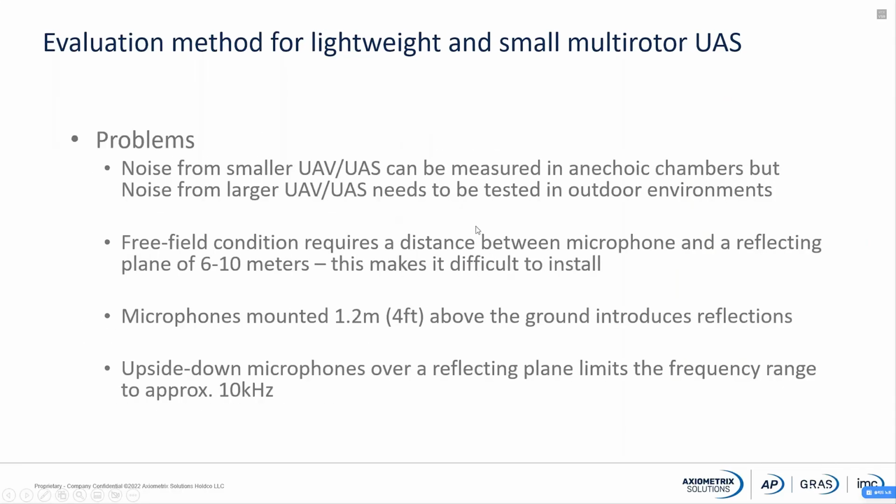So the problems we are facing are that we can do some measurements in anechoic chambers, but noise from the larger UAVs needs to be tested in an outdoor environment. Free field conditions require a distance between the microphone and the reflecting plane of 6 to 10 meters. This makes it difficult to install and costly.